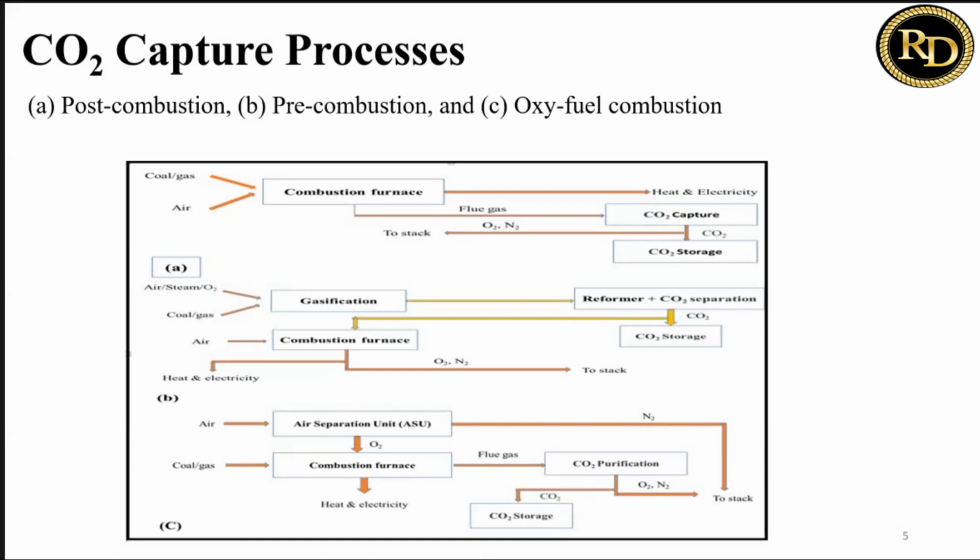For example, in a system, if the flue gas is emitted and after flue gas emission the carbon dioxide capture process is introduced, then this is considered post-combustion. And pre-combustion is where the fuel gasification step and the carbon dioxide capture step are introduced before the actual furnace and emission of the flue gas. Then it is pre-combustion carbon dioxide capture.